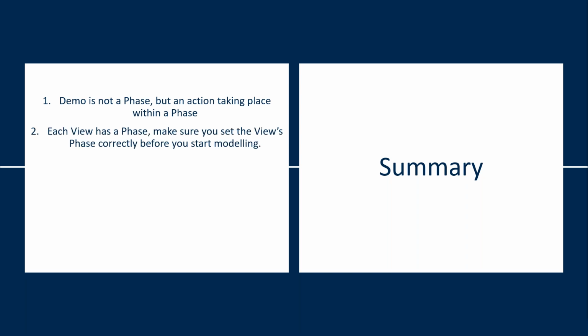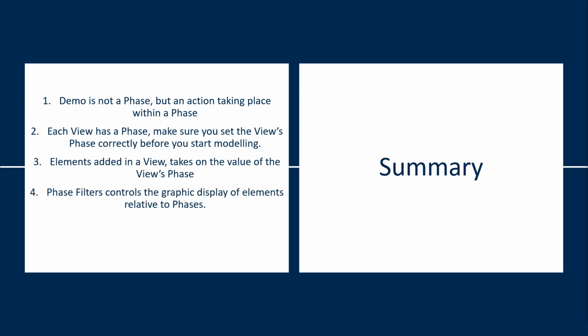And that brings us to the end of our session. So I would just like to end off with a quick summary and just some thoughts to take away from today. Remember, demo is not a phase. It's actually an action taking place inside of a phase. And then each view has a phase. And always make sure that you set your view's phase correctly before you start modeling to ensure that your elements are added to the correct phase.